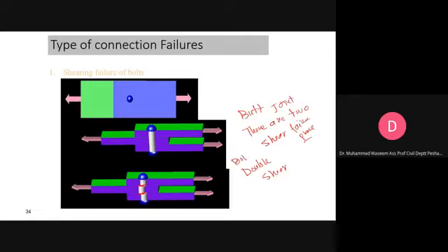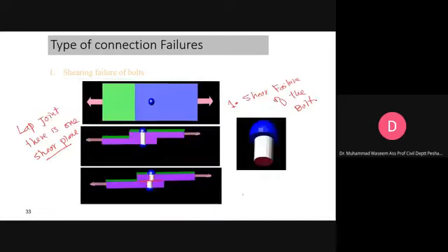In the other case, we term it that the bolt is subjected to single shear. And what is the area of the bolt which is being used for computing the shear strength of the bolt? This is very simple. AB is equal to the diameter times this one.